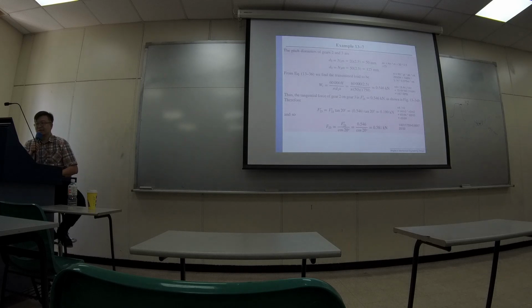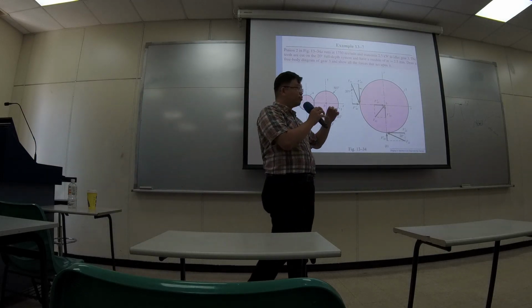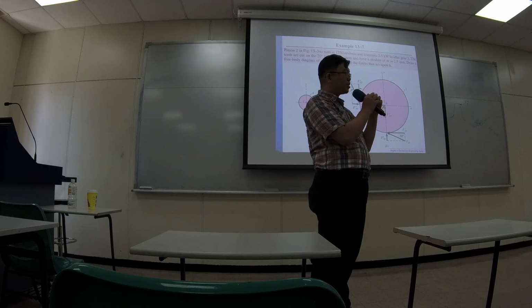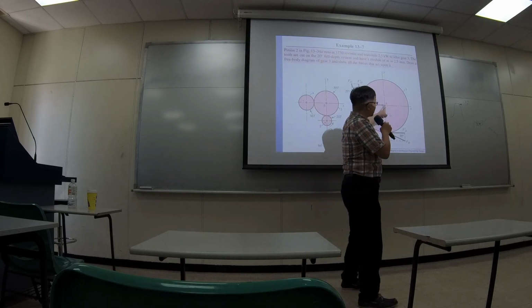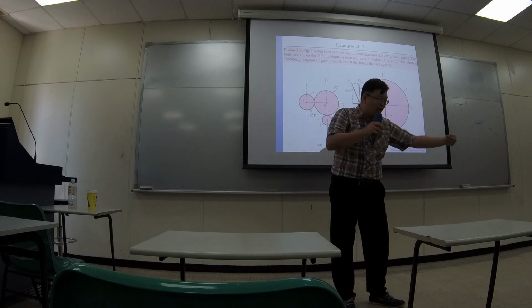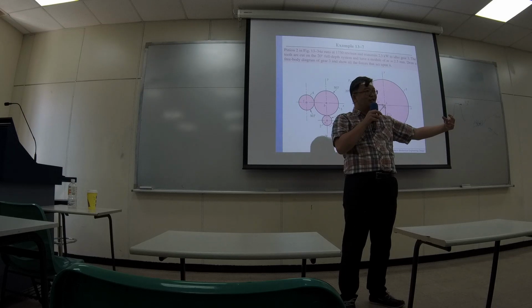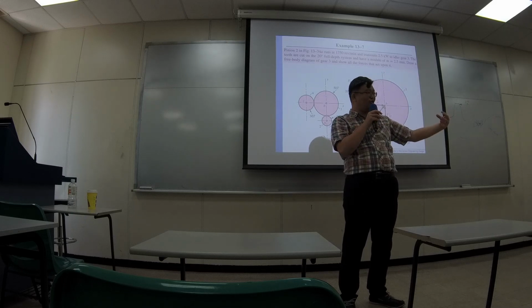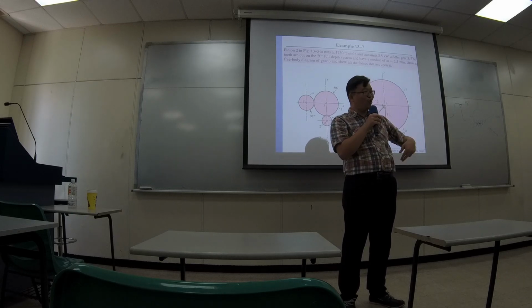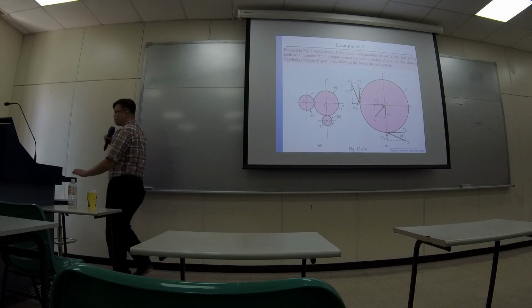Okay. So this part is telling you how to calculate it. Usually for a shaft system, you have to design for the gear pairs, study the force being applied between the gears, then study the reaction on the shaft, and then go back to your shaft to figure out how much force is being applied to the shaft. For that shaft, you need to do whatever we did for the first couple of weeks. You have a shaft design, you have shear force, moments, and so on. Then you know whether the shaft can carry the loads.